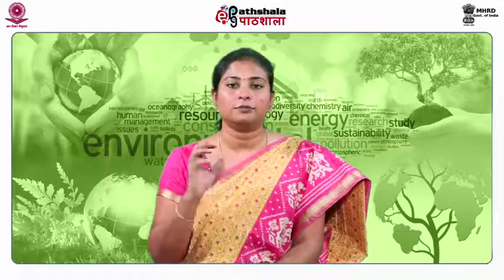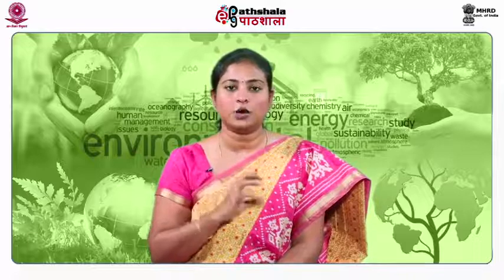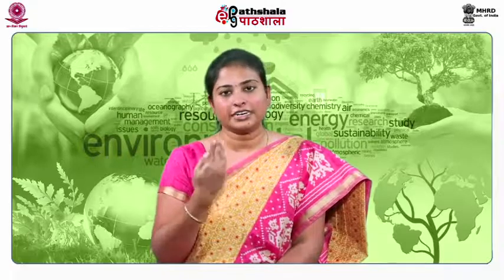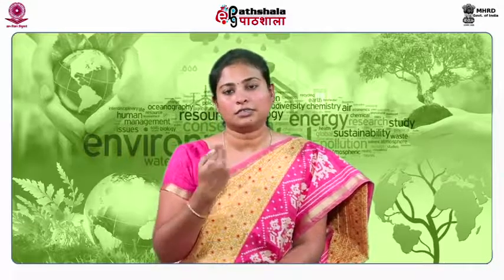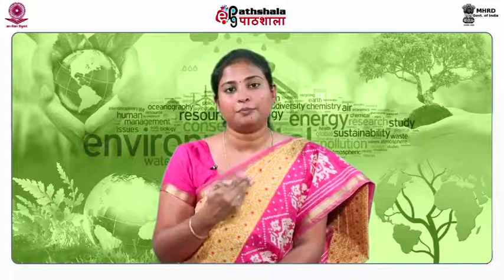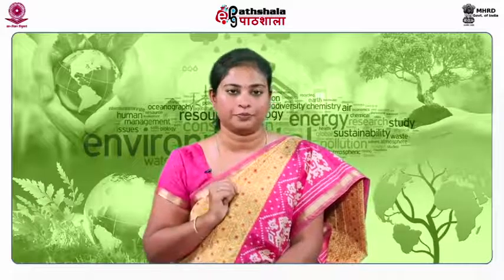Then you should continuously monitor gas flow and quality because when you analyze the quality and quantity of gas generation, that will again indicate the biological activity going on inside the landfill bioreactor, and this information will also be required for expansion of the plan and modification of gas management systems.